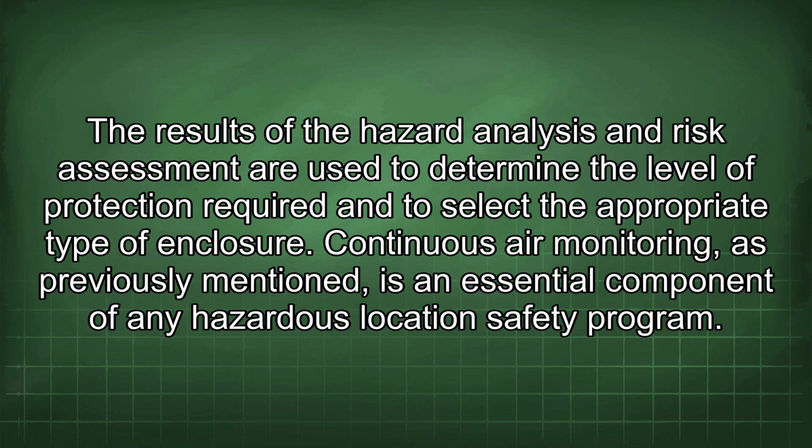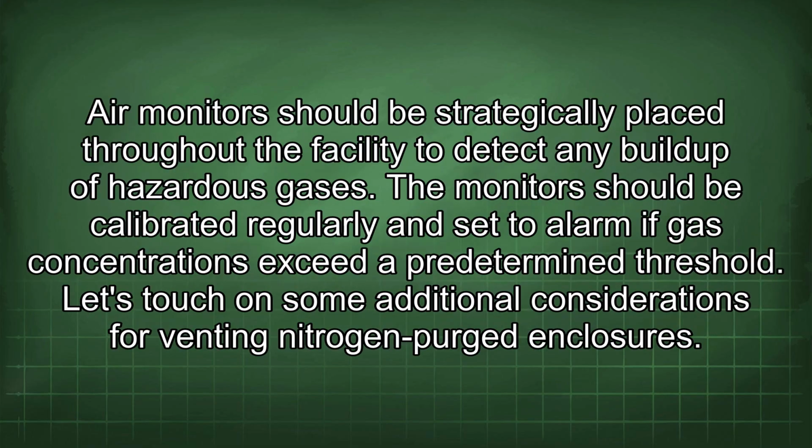Continuous air monitoring, as previously mentioned, is an essential component of any hazardous location safety program. Air monitors should be strategically placed throughout the facility to detect any buildup of hazardous gases. The monitors should be calibrated regularly and set to alarm if gas concentrations exceed a predetermined threshold.